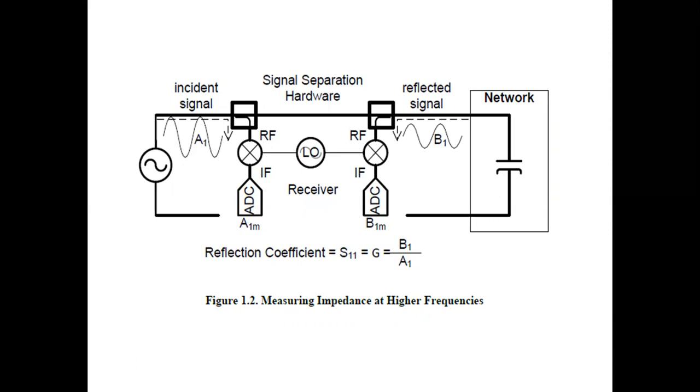myriad of passive components that includes cables, filters, switches, duplexers, triplexers, couplers, bridges, transformers, power splitters, combiners, circulators, isolators, attenuators, antennas, and many more. In addition, one can characterize active devices such as transistors and amplifiers using S parameters, as long as they are operating in the linear mode of operation. These high frequency devices can have one or more ports.